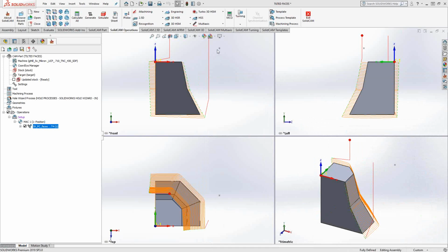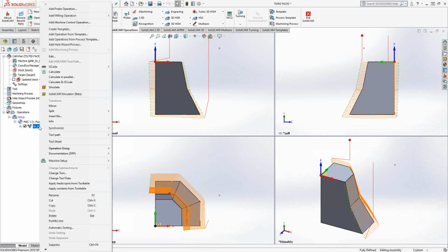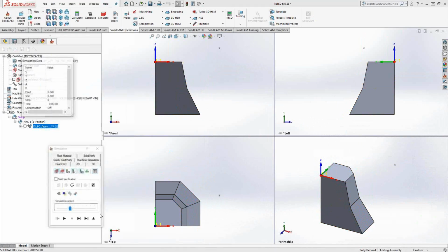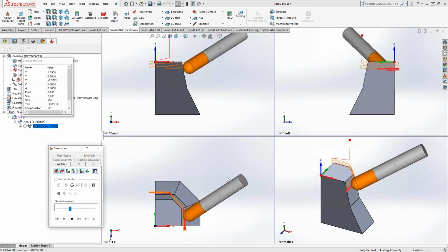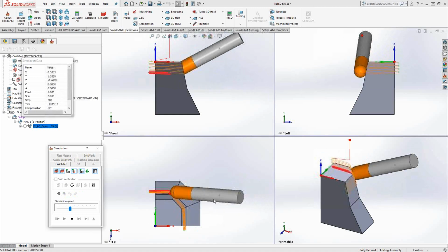This point you see here I've sketched out in space is going to form a vector for the tool between the point and where the tool actually contacts those surfaces. And you can see from the wireframe that the toolpath angles actually pass through that point. If you look in the bottom left corner and the top left corner, you can see that those are the angles that tool takes. If we do a simulation on that and play through that, you'll see that the tool is always passing through that point. The vector made by the tool is always there.